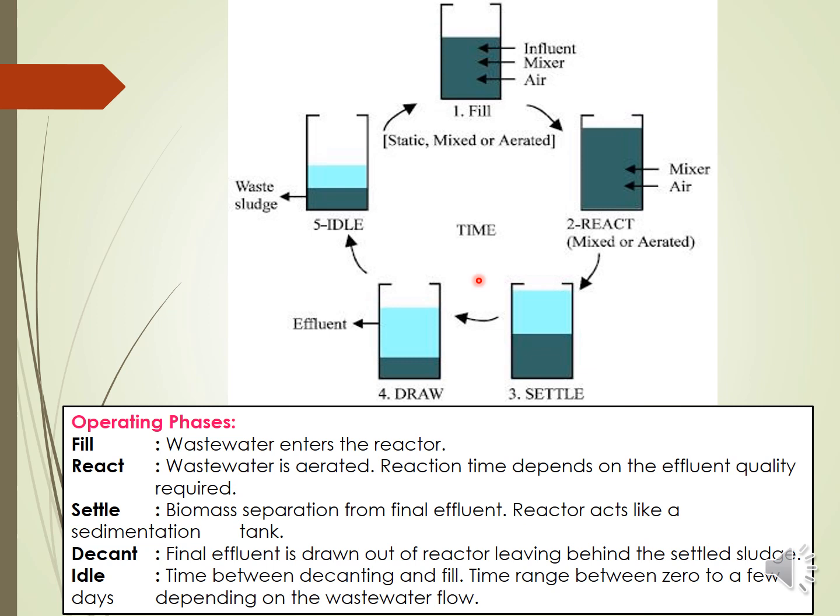of the tank. And this will be after the sludge is settled. And finally there is a final stage or final phase, which is the idle. This is a time between decanting and filling. It ranges between 0 to a few days sometimes. It depends on the wastewater flow or the design of the wastewater system.